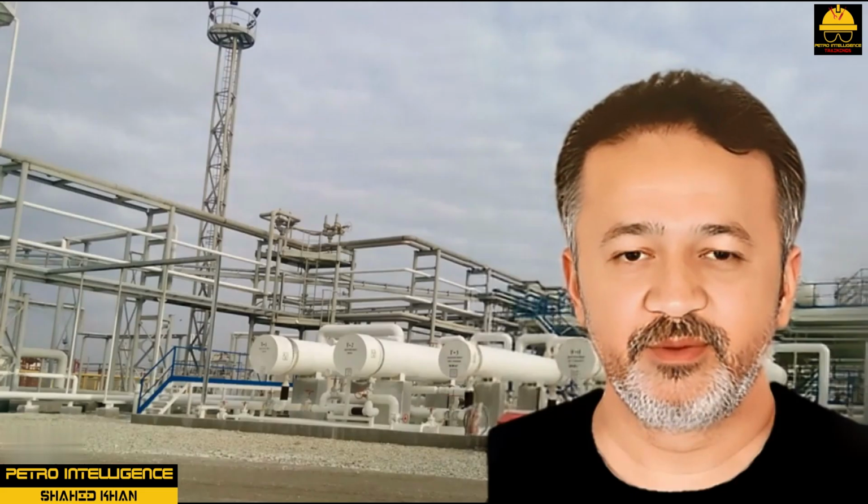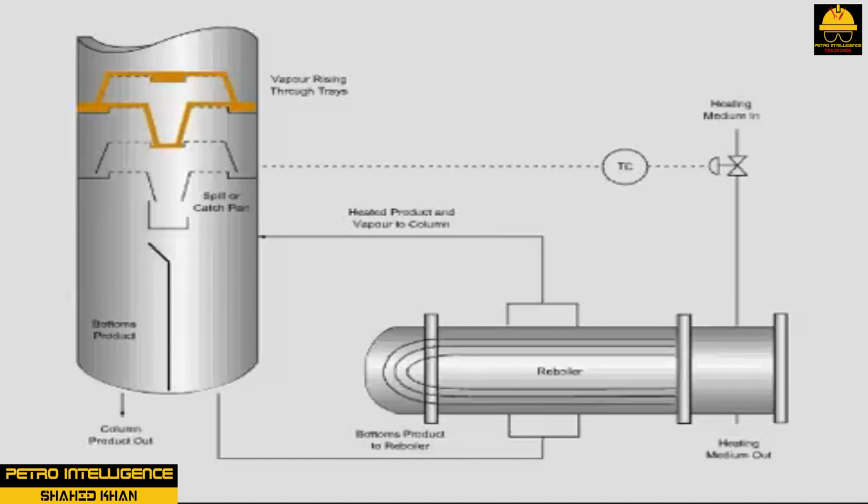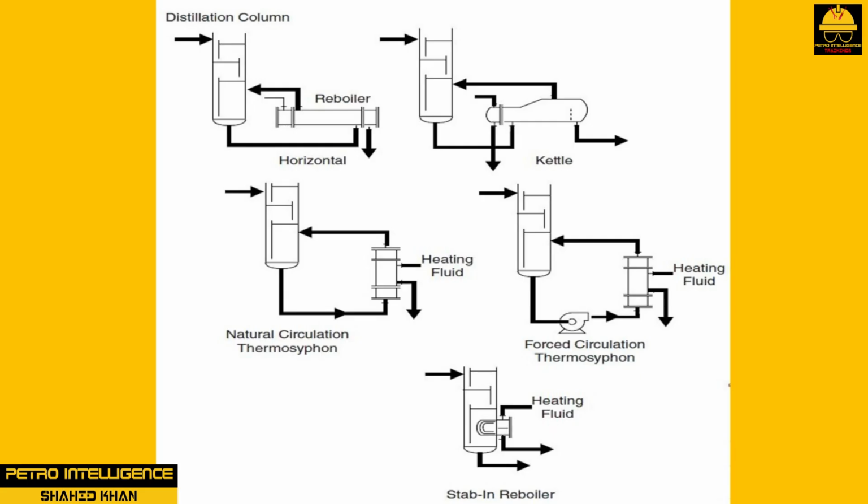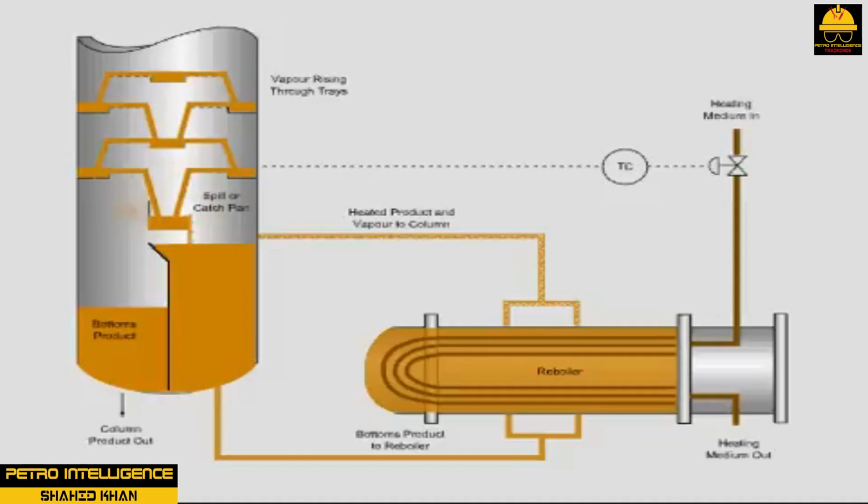Reboilers. Reboilers are used to add heat to a liquid that was once boiling until the liquid boils again. Reboilers are closely associated with the operation of a distillation column. Typical reboiler arrangements include 5 basic patterns: flooded tube kettle reboiler, natural circulation, forced circulation, vertical thermosiphon, and horizontal thermosiphon, as shown in picture. These types of devices are classified by how they produce fluid flow.